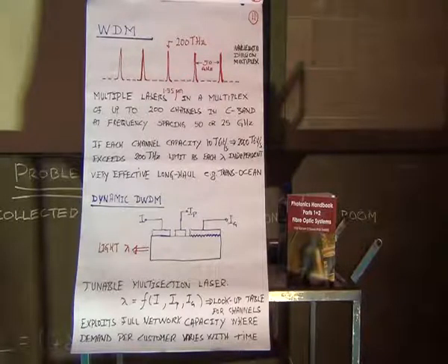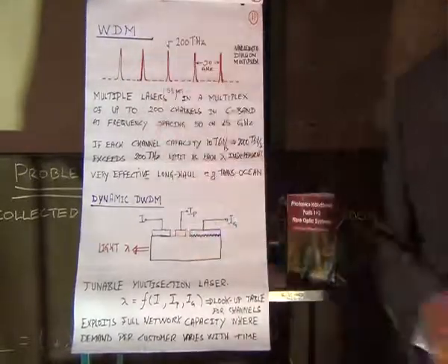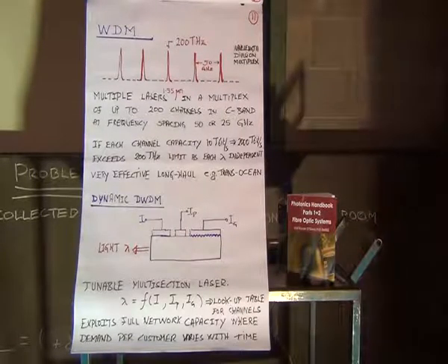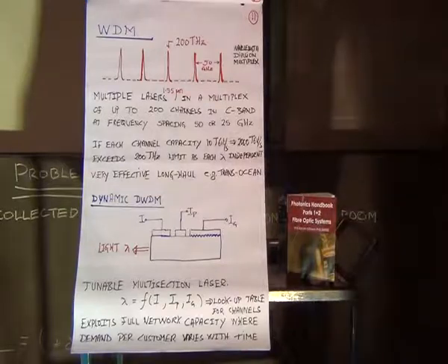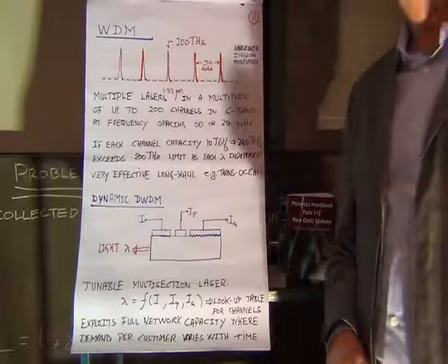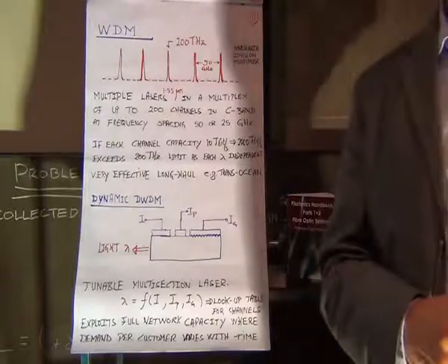Of course, you can imagine that going on throughout the city, throughout the nations of the world, that as demand changes all the time, you can dynamically reassign the channels using these tunable lasers. You could even do one further thing, and I'll finish on that. You can build a little grating like this into a section of an optical fibre. Okay? And that fibre Bragg grating, as it's called, will transmit some wavelengths and reflect others.